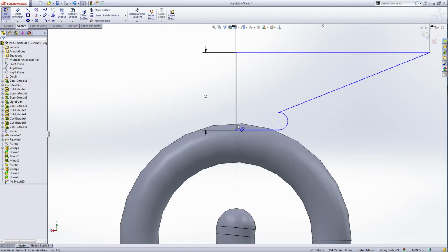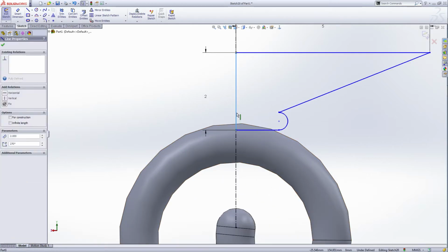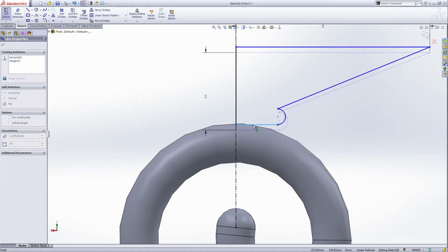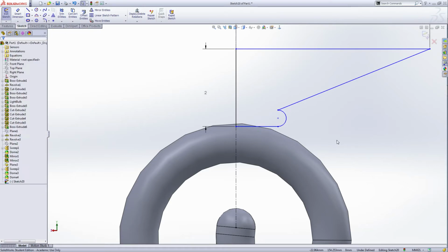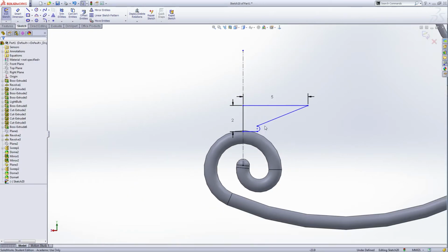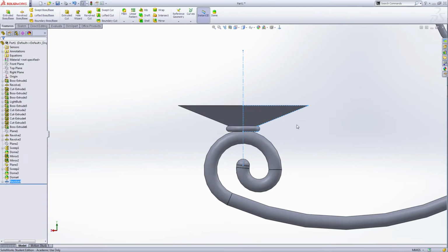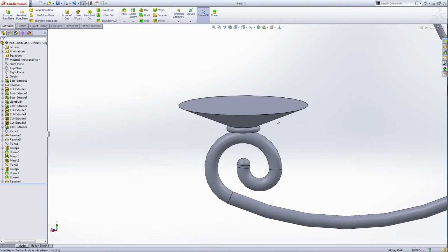I want the result to merge together, so this supporting frame is a little bit inside this supporting frame, so leave it like this. Okay, I only want to fix this direction and this direction. All the others are okay. So exit the sketch and revolve like this. Check. Now the supporting frame diameter is 10 millimeter.